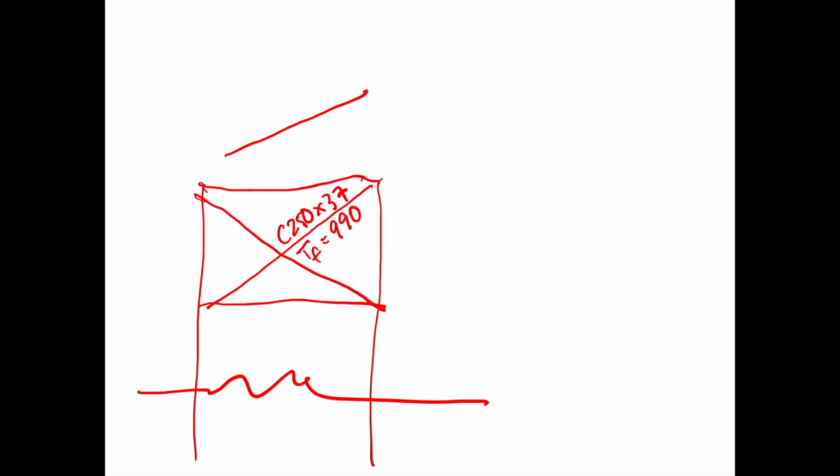The engineer is usually going to round it up a little bit. Very rarely would you see 983 written on the drawings. And that's the information that the fabricator is going to be working with to try to make a channel work. Okay? In this case, I didn't look at the radius of gyration. I probably should have, but I already know that we're not going to be able to make slenderness work here. The radius of gyration for this section is quite small. The slenderness ratio is probably going to be 400 or 500. So I'm going to need to do something to take the slack out in the field, and I'd specify that on the drawings.